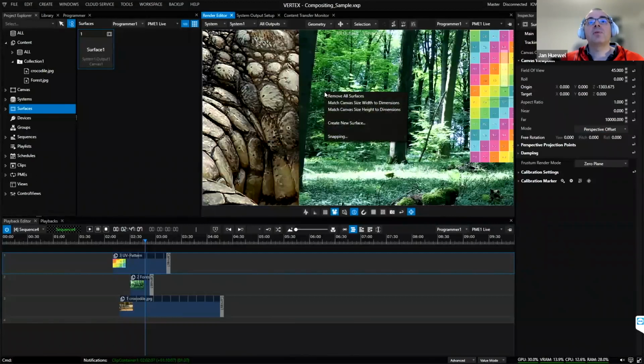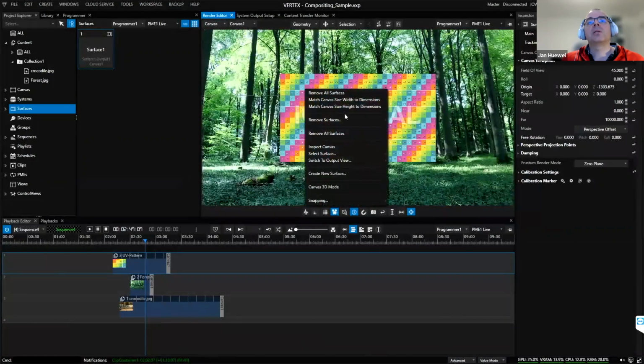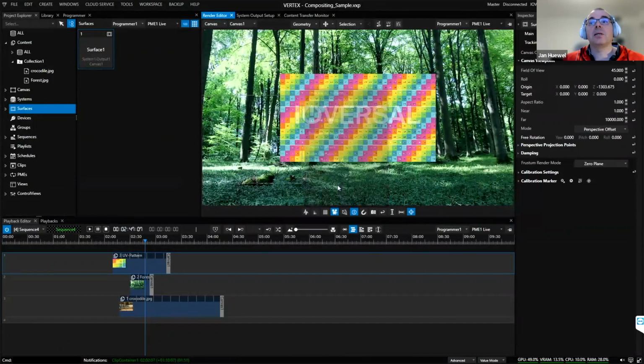If you right click on a canvas, I think it's in canvas space, you can switch to canvas 3D mode, and then it will change these to a different default. This will then probably cause Z-fighting, and right now it goes to +1, which is less accurate for 2D but more accurate for 3D objects. So this is important when you move complex 3D scenes.